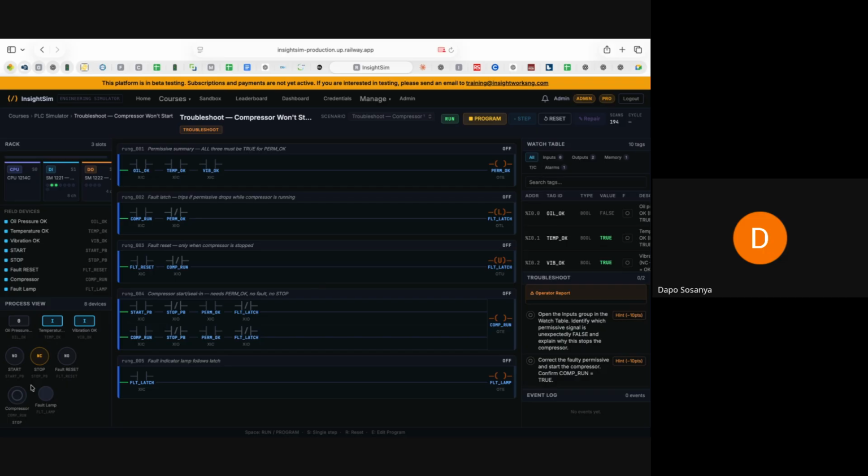Right? So if I come here and I start, if you look at this rung 004, you see that the compressor attempts to start, and look at what stopped it. This perm_OK, because this is still false. It is not true, right? The compressor couldn't start. Can you see that?